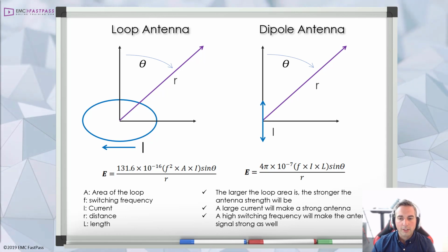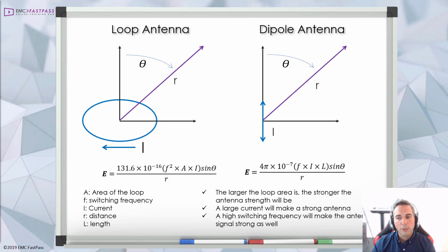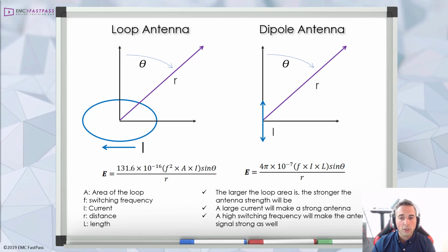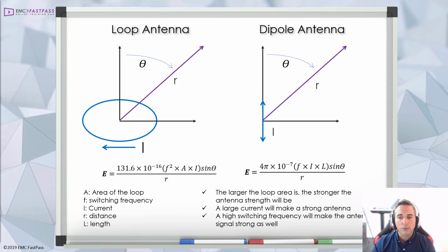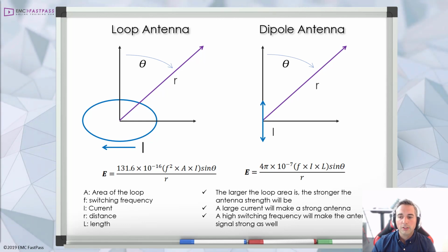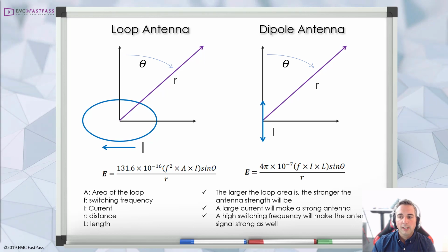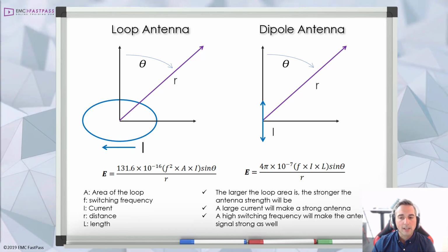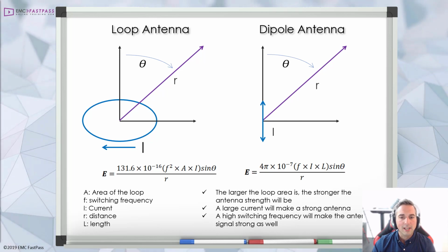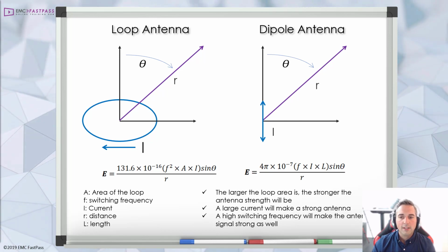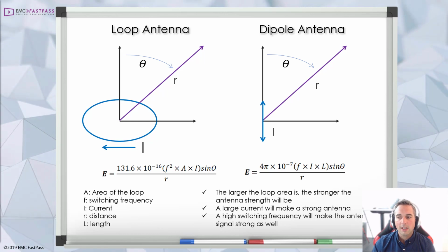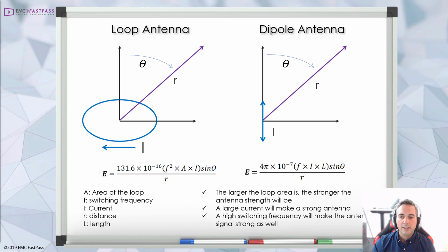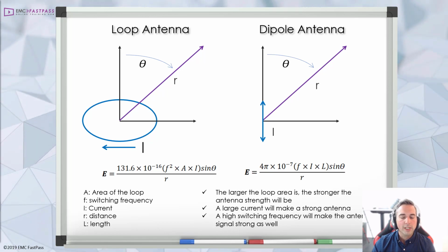Dipole antennas, on the other hand, are more synonymous with common mode currents. And they're the currents that we don't typically want to occur in our circuits or systems. Common mode currents on external cabling is one of the most common sources of emissions failure mechanisms at an EMC test lab. I just wanted to give you a heads up that these two different types of antennas can be associated with the two different types of current that we'll need to think about when we're trying to control radiated